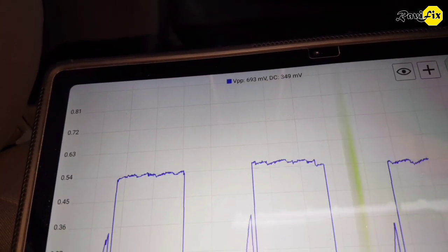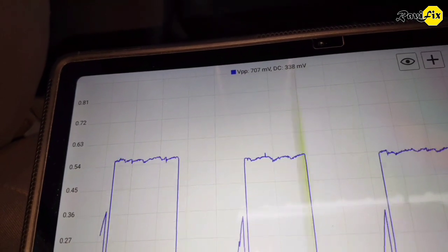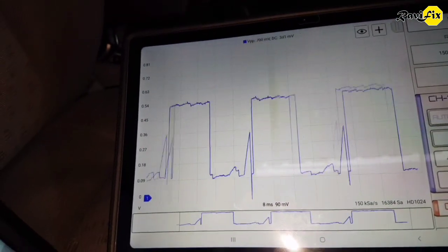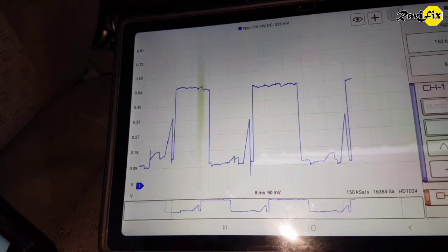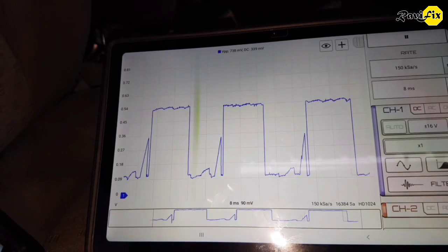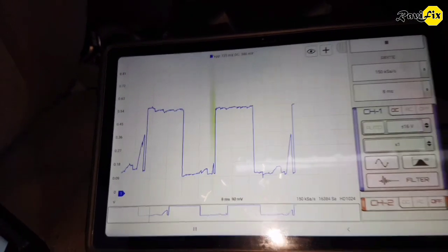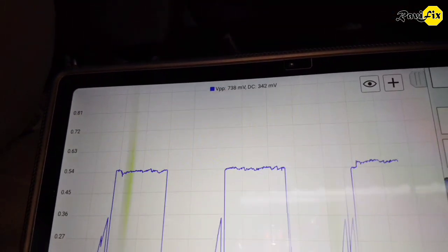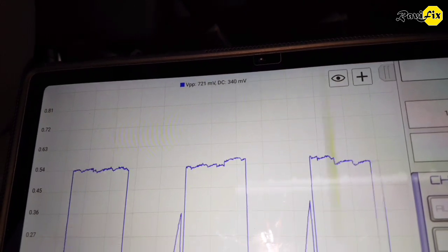That should be a square wave at around battery voltage. Definitely this signal is not normal. That is why we are not getting the RPM signal into the tachometer and the TCM. The next abnormality is, do you see that voltage ramp near every rising edge of each square wave? That might not be normal. It seems the signal is shorted to ground somewhere, or the ECM produces a bad engine speed signal.